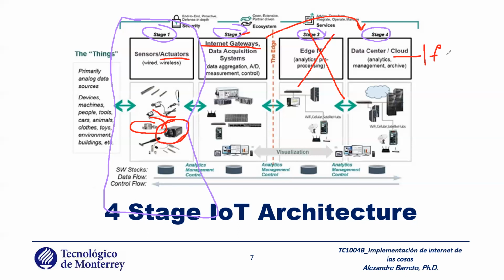For example, if the temperature is between 27 and 30 degrees Celsius, it is good. If it's outside this range, you have a problem, and you generate an alert. The cloud is one place where you can install this function, okay? Another thing you can have in the cloud is machine learning algorithms to detect, for example, trends or patterns, okay?